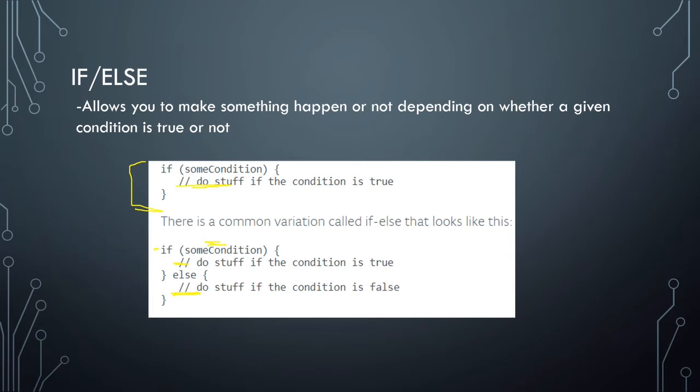If the push button is being pushed, turn the light on. And so we could fill this in. The only drawback to that is that we could let go of the push button and the light would stay on. There would be no code telling it to turn off, unless you had it stay on and then you gave it a delay and then had it turn off.